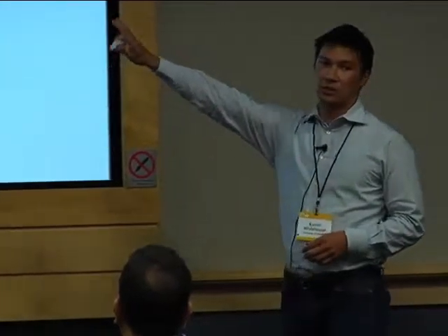So what's actually in this door jamb sensor? There are a number of things here. One is a motion sensor. It's pretty simple. There's one on each side of the door to monitor motion in both directions. There's also a door latch sensor, so it can tell, for those doorways that have doors at least, whether the door is open or closed. Inside this enclosure, in our current version, which you'll see a little bit later today, there's a temperature sensor, two light sensors, one in each direction, and a magnetometer. And the last and most important sensor here is an ultrasound sensor that points down. It's actually an ultrasonic rangefinder, pointing down into the bottom of the doorway.